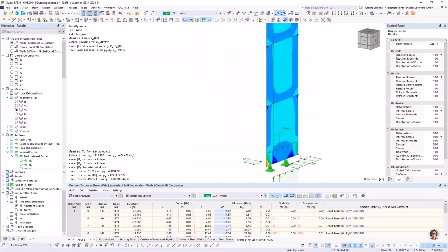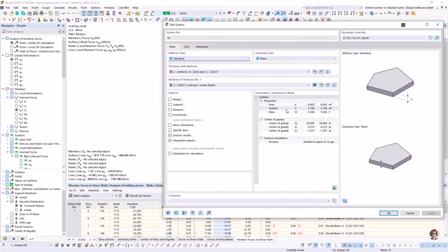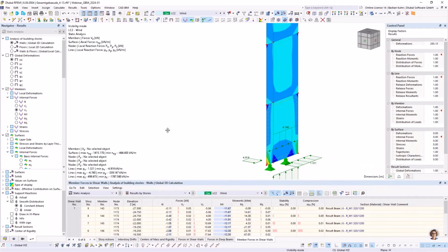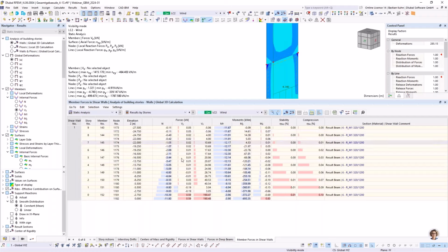You can see, okay, load transferring is, as I already mentioned, done by the surface itself. If you model it to have a reduced stiffness, if this would be a CLT wall, it would include the reduced stiffness. If you have defined a line hinge in here, that would be regarded. But right now I did nothing with it. It's using this shear force in between, and that's the result that I have. Of course, I can always have my shear force integrated here via the result beams. This is also done automatically by this add-on building model.